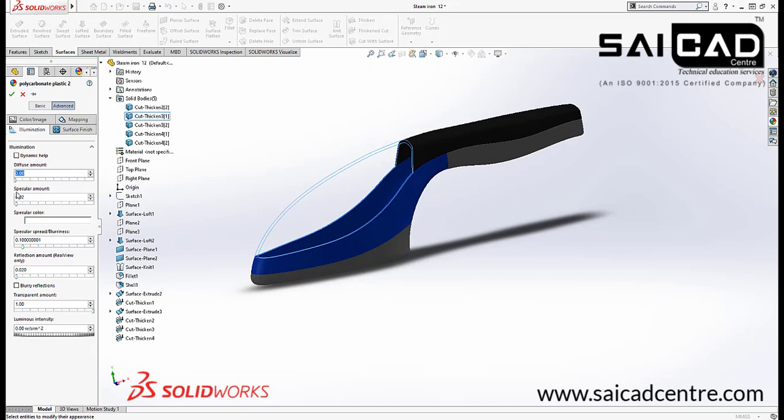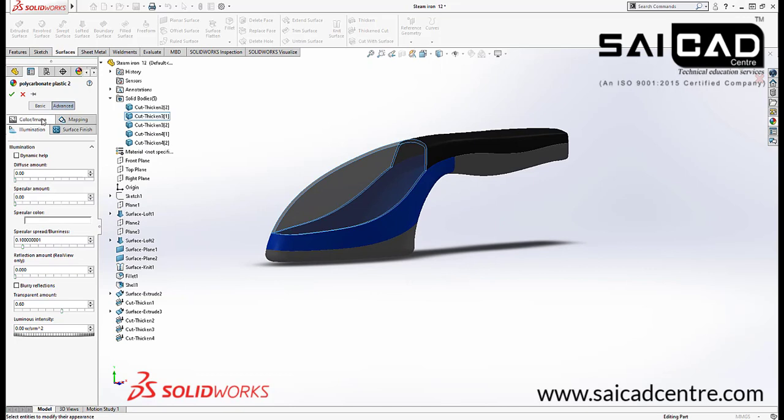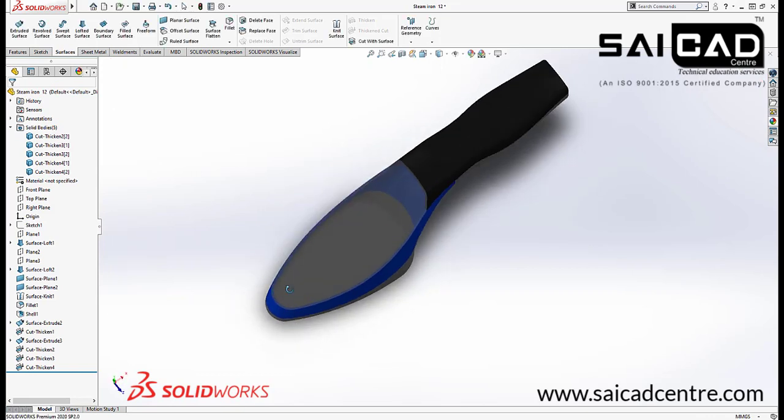Okay, no change. Specular amount, no change. Okay, reflection amount, no change. Okay, we have the transparency. You can see transparency is 1. I can just reduce the transparency, and you can see that we have some object like that. So go to the color, you can add a different tint from here like that, whichever you need. Okay, so I need somewhat this one. Click OK, and we have the body right here.